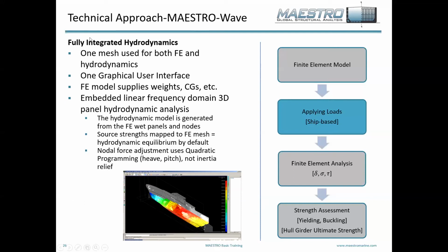Now, Maestro Wave, as we said, is a fully integrated hydrodynamics package. One of the major advantages to this is that because it is fully integrated, you only have one mesh for both the finite element model and the hydrodynamics runs. So it can eliminate some of the error from having to map the loads from one mesh to another.